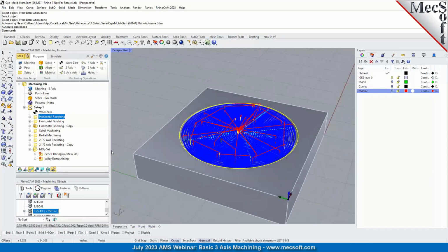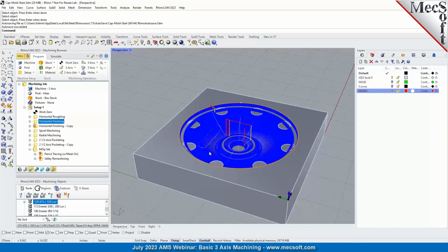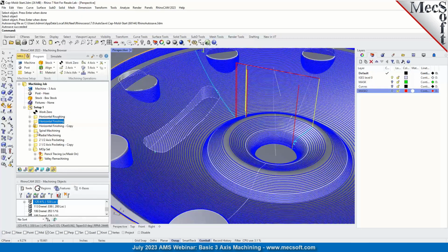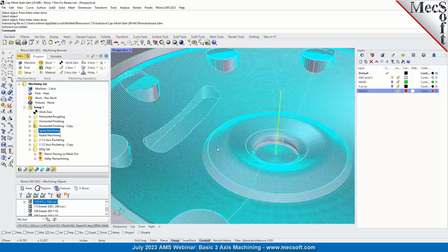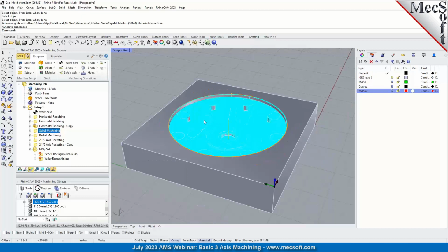We'll just go through and look at the tool paths, roughing, finishing, spiral. Now, one thing I can point out here is that in spiral and radial, you cannot fit arcs. Arcs can only be fitted in the 3 principal planes of your part, and that's all that the CNC routers will support. For instance, if it's going along the X direction, you can put an arc. If it's going in the Y direction, you can put an arc.